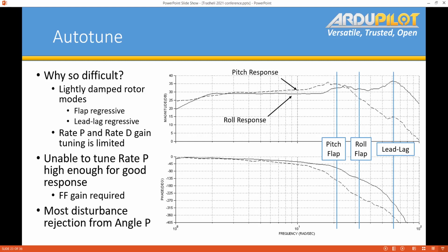And you do it at a certain frequency. At lower frequencies, you'll notice that the aircraft will maintain the same amplitude that you're basically pumping the stick at, right? But then as you increase your frequency, you'll see that the amplitude will start to actually die off as you go to higher frequencies. And that's effectively what that's showing here, is that as you go to those higher frequencies, your amplitude ratio or your magnitude is going to die off, your gain.